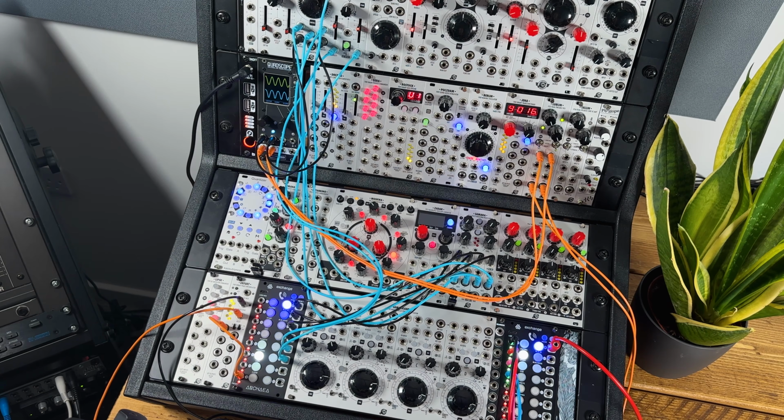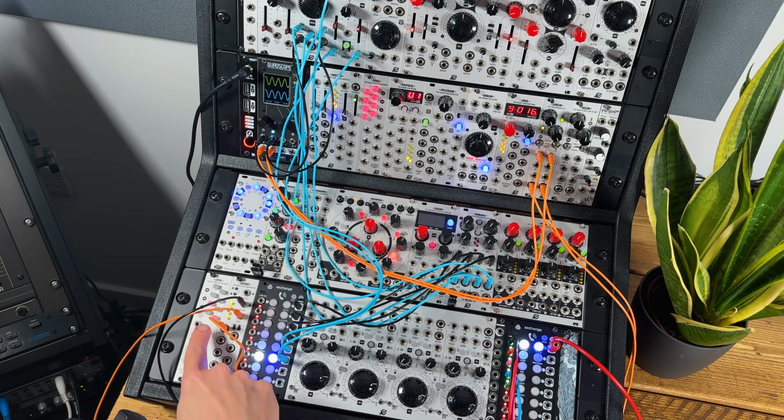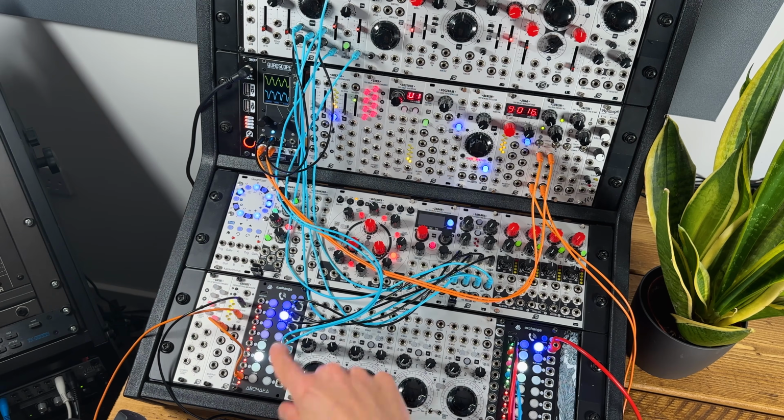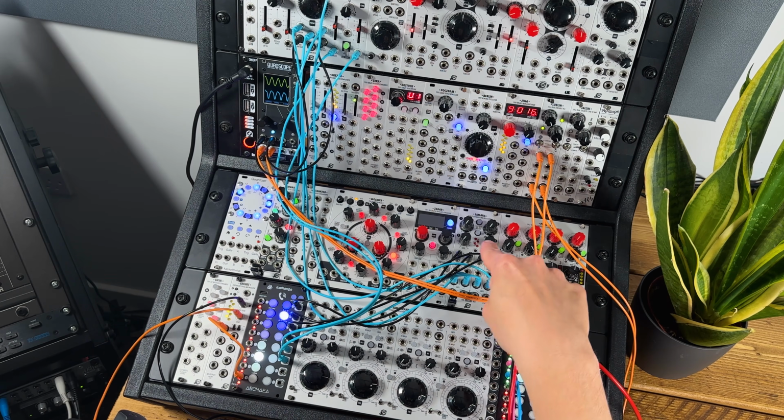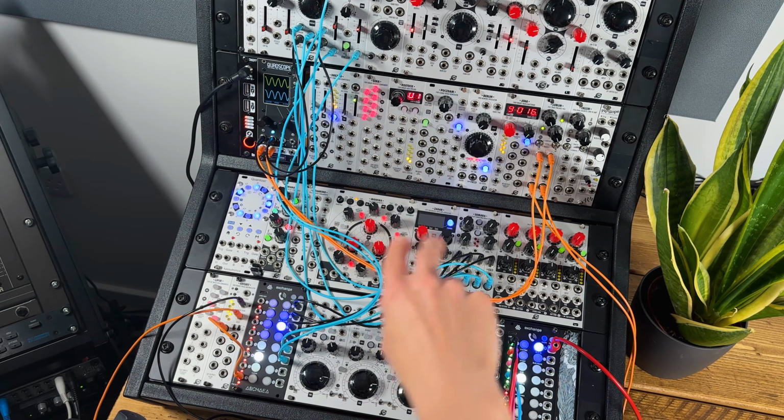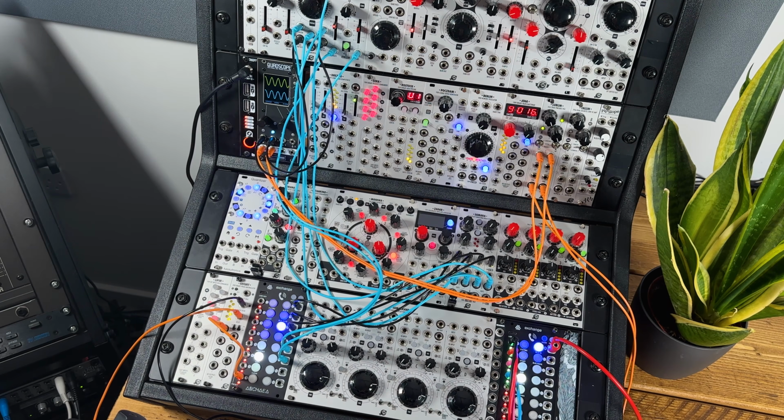In this one, what I've got set up is the left-hand Exchange is connected via Leibniz underneath to Erfurt, which is basically acting as a trigger sequencer. I'm feeding in a clock and setting a counting interval with Lipsk, and then the 8-bit outputs that come into Exchange are putting out these gate patterns, which you can see flickering on the LEDs there. I'm routing some of those outputs through Samara for attenuation, and some straight into Odessa, which you can just see in the very top left of the picture.